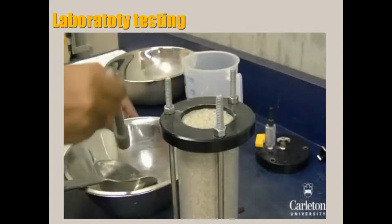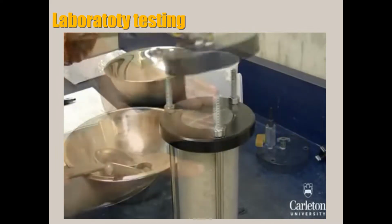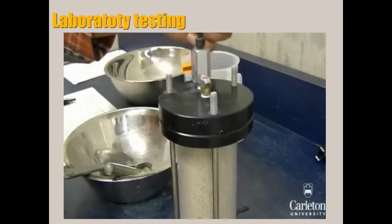Level the soil at the top of the cylinder. Place the second porous stone on top of it, and then thread the end cap on, securing it like this.